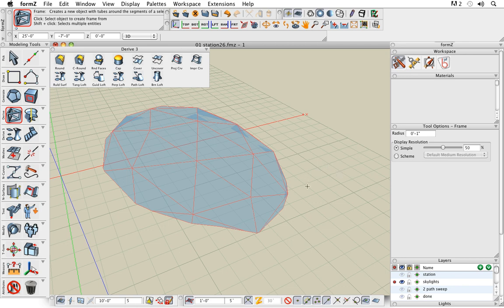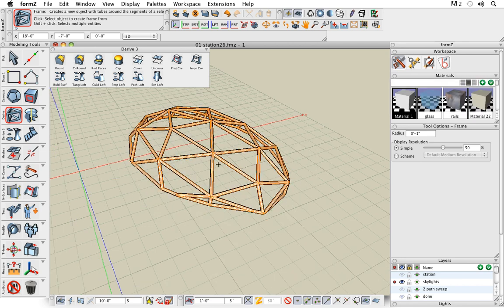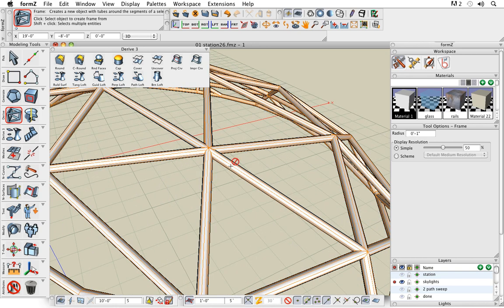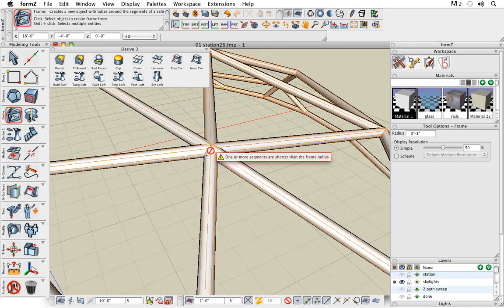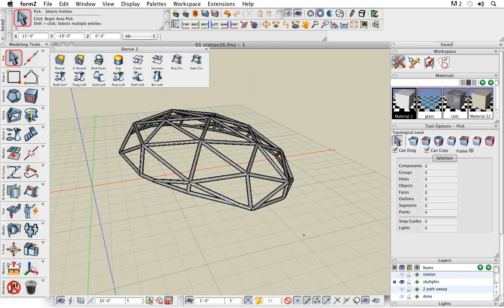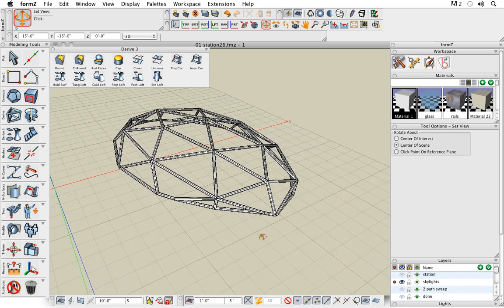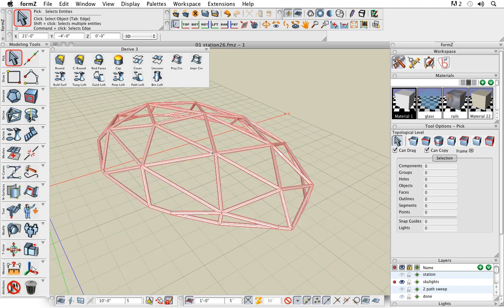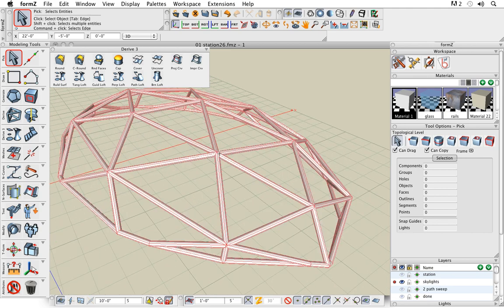And it'll not only create the framing members throughout all those edges, but it'll also properly resolve the intersection of where all those edges come together to the same point. So I zoom in here, I can change the radius. We're in this orange result buffer mode, so I can change the value if I want. Maybe it's too large, too small, whatever. Change it, it'll automatically update for me. So now we've got a nice quick conceptualization for the framing of that object. Now that is a true solid object, so we can still do Boolean operations and things like that on that if we want.